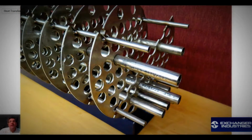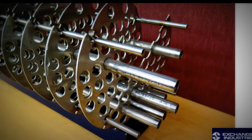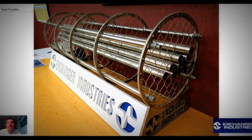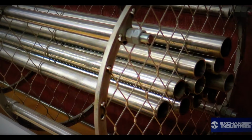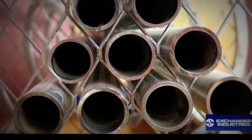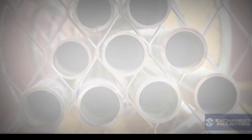And there we can see a closer in view of the spiral baffle. And this is M baffle, where it's a longitudinal, basically a double pipe heat exchanger. These baffles essentially create a lot of turbulence and enhance mixing, again reducing fouling. So those are some of the different types of heat exchangers that we're going to be looking at. It gives you an idea in terms of where heat exchangers are used.